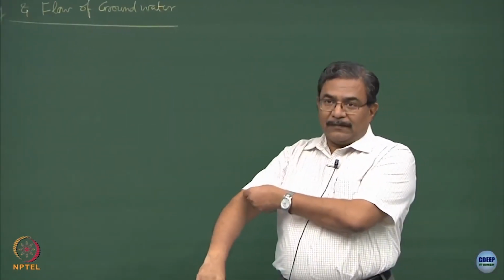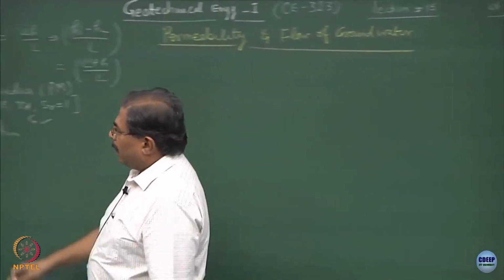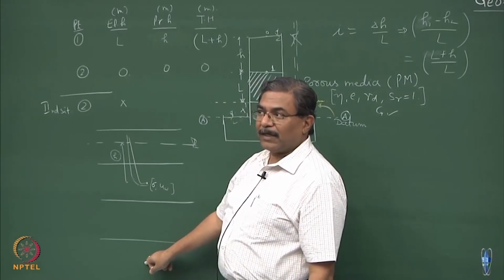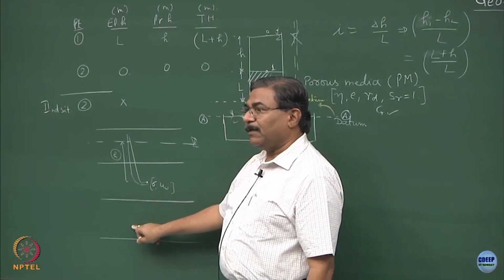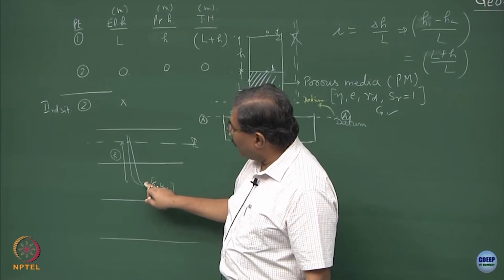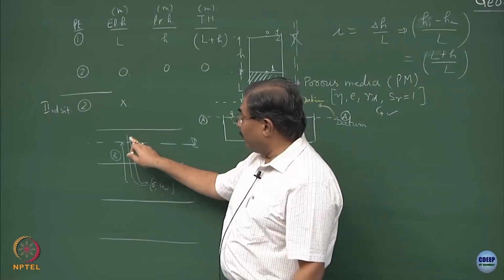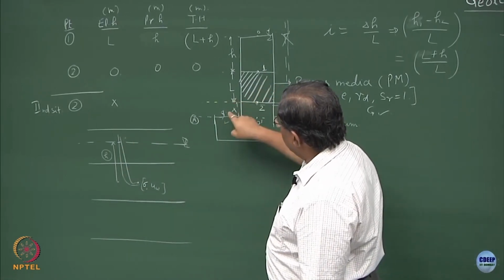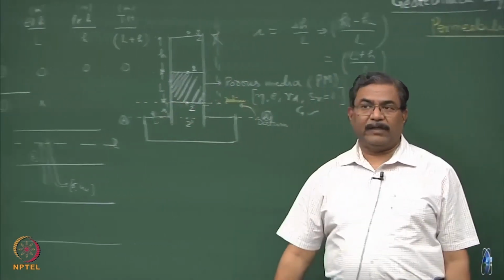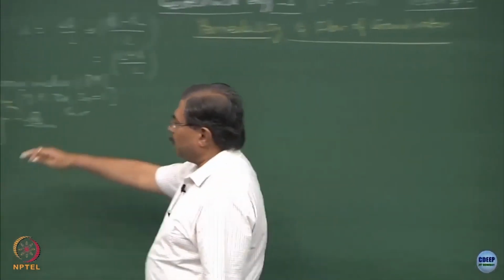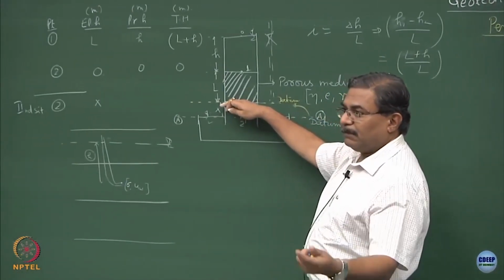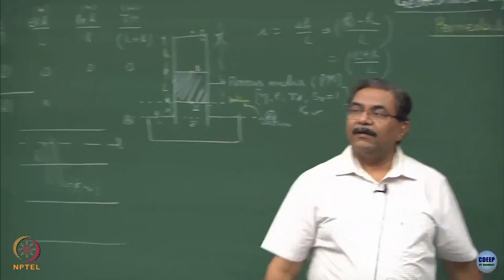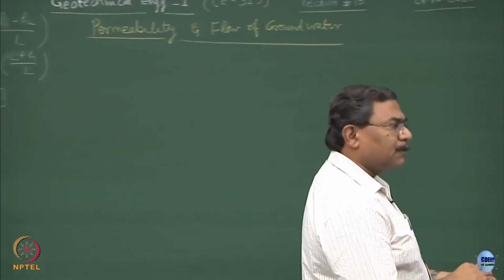And that is what you have to understand. Here the boundary conditions are different as compared to this. This is a continuum, which is not exposed to the atmosphere. So, if you install a piezometric tube over here, this will go and meet the phreatic surface. But in this case, at this point and this point, the atmospheric conditions prevail. So, it is a good idea to shift the datum to the bottommost point of the sample. It becomes easy to go ahead with the analysis. Is this part clear? This is the discrepancy which I wanted to discuss in the last lecture. Is this part clear?